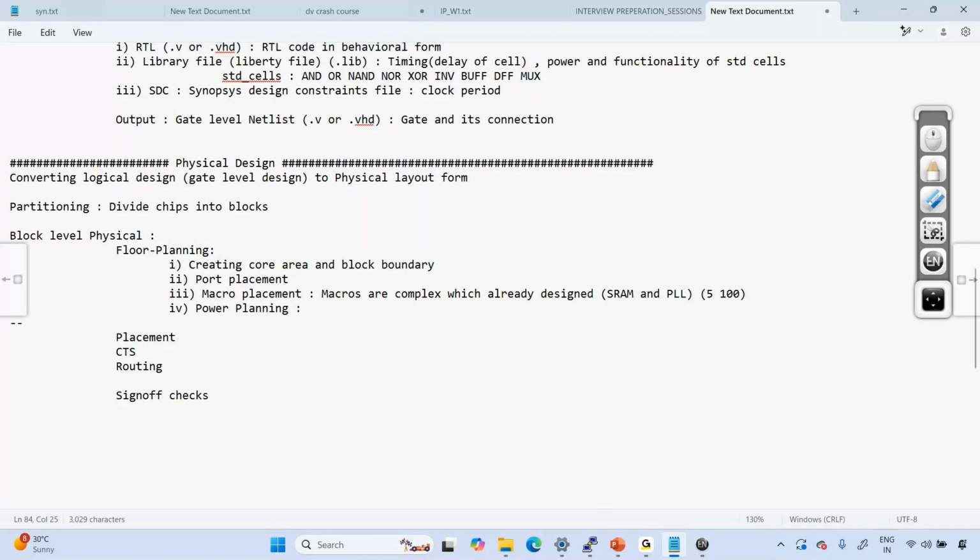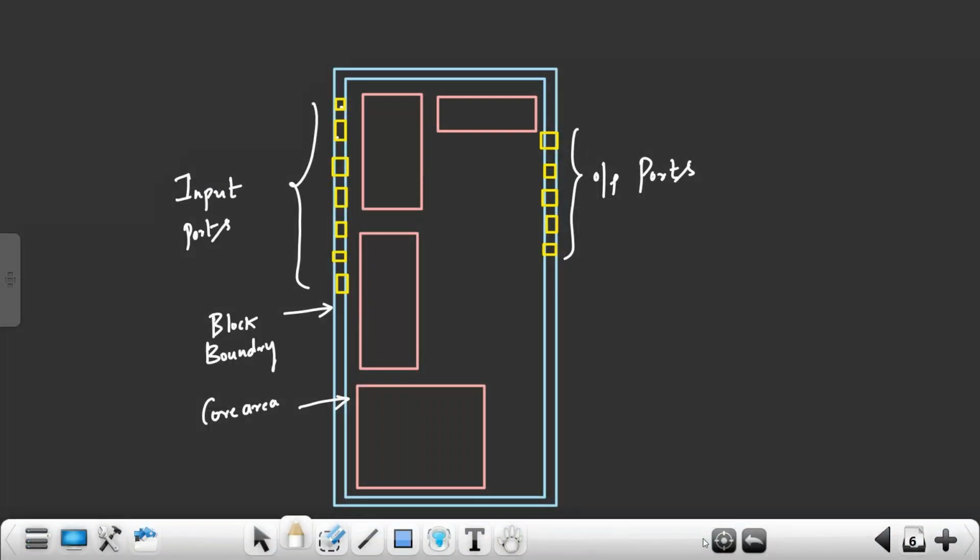What is IR drop? For example, assume I have one cell here and one port here. This is the VDD port. From this port I am directly connecting to this cell's VDD through a metal layer. Now when this cell is switching, it will conduct current, and current will flow through this.